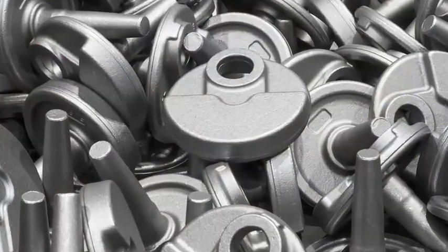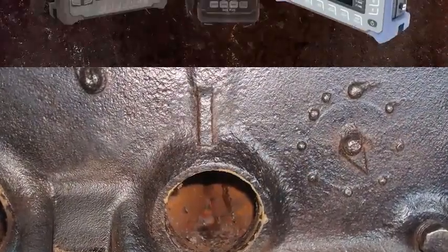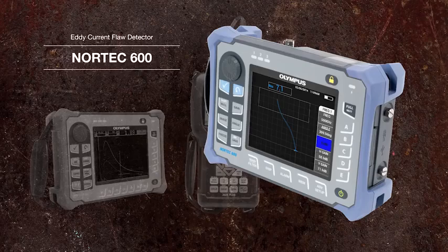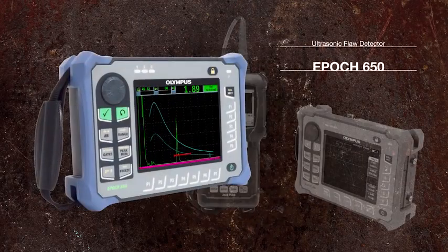Due to these characteristics, there are a number of non-destructive testing techniques that apply to cast components. These include eddy current tests for surface cracks, an ultrasonic test for thickness, porosity and voids, and graphite nodularity.